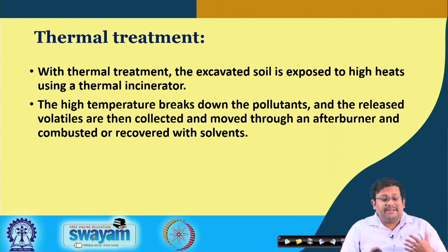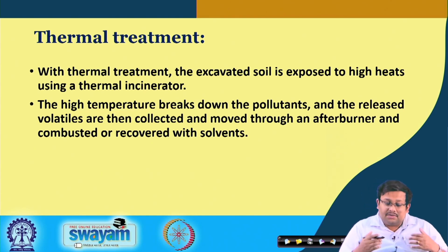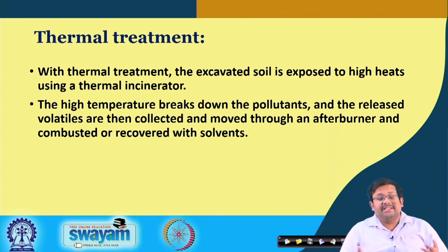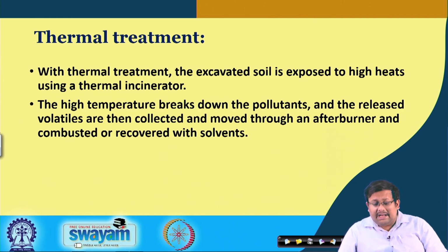Now, the next treatment is basically known as thermal treatment. Sometimes we call it incineration. Remember that with thermal treatment, the excavated soil is exposed to high heat using a thermal incinerator, and the high temperature breaks down all the pollutants and releases different types of volatiles, which are then collected and moved through an afterburner and combusted or recovered with different types of solvents. So, this is how the thermal treatment basically works.